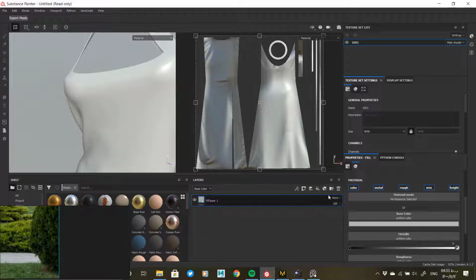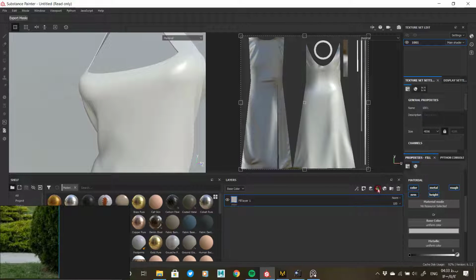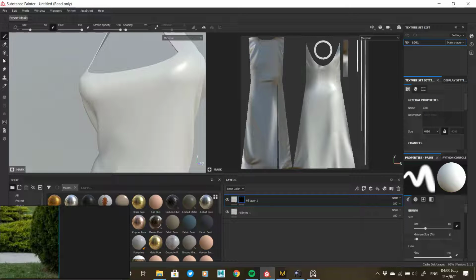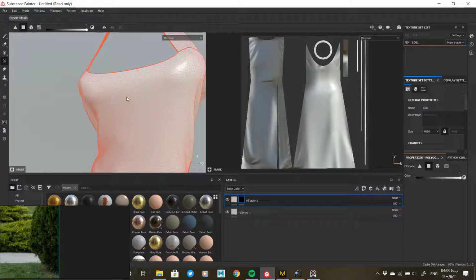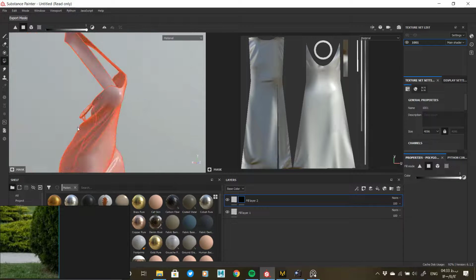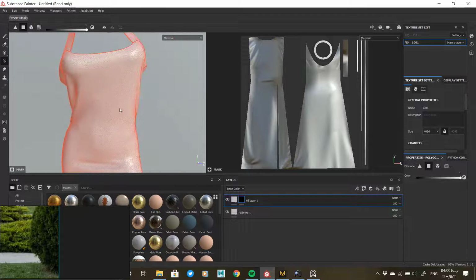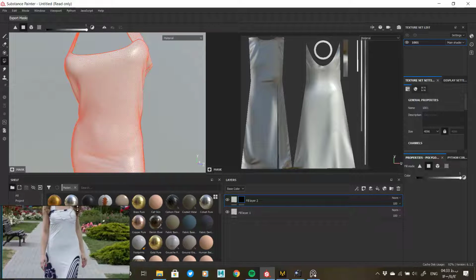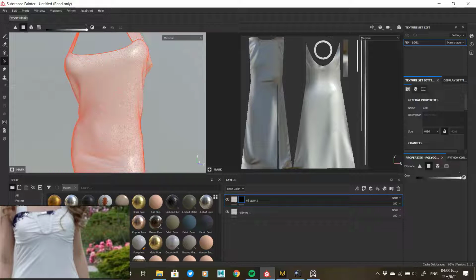Now it's time to start materializing. Open Substance Painter and enter the low poly model. If we have a model without thickness, it is better to change the type of shader, so that the normals appear on both sides of our screen. Now we see in which of the poly groups we specified, it is applied as a texture list.